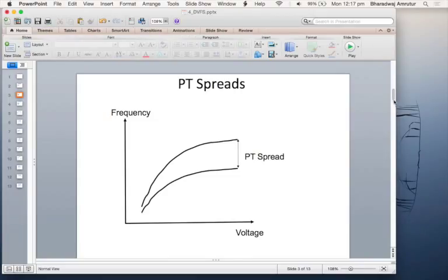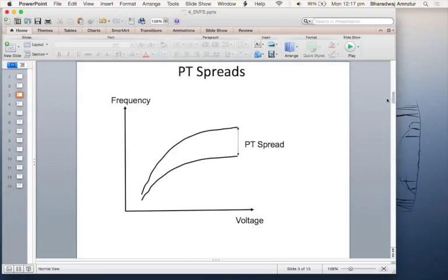So what these two curves are capturing are the limits for a particular design in a particular process. When you randomly take chips from that factory across a period of time, their frequency to voltage mapping will lie between these curves.